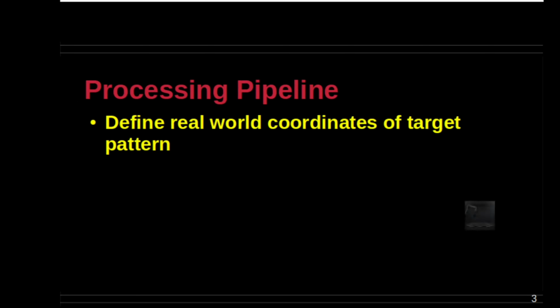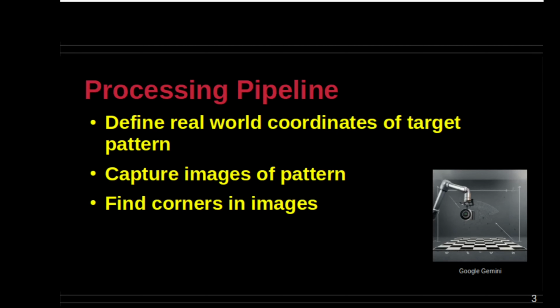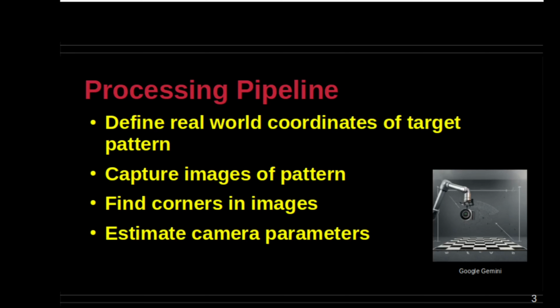While it is possible to use different patterns to calibrate the camera, the basic requirement is the presence of fiduciary markers on the object. The checkerboard fulfills this requirement with its intrinsic corners. The checkerboard pattern, that is the number of internal rows and columns, is a user choice. For our calibration exercise, we have several different checkerboards with differing number of rows and columns.